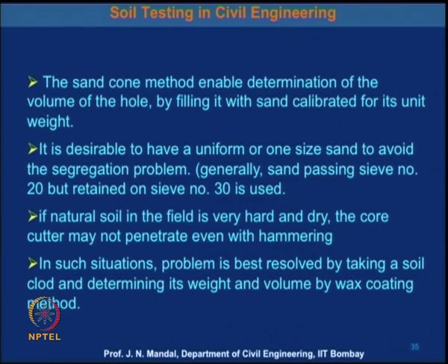In such a situation, the problem is best resolved by taking a soil clod and determining its weight and volume by the wax coating method. So, this way you can solve the problem if it is too hard. Different types of methods are available, so depending upon the type of the soil you can adopt one and determine the properties of the soil.